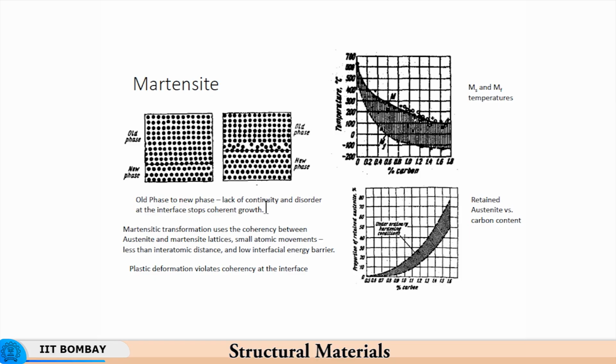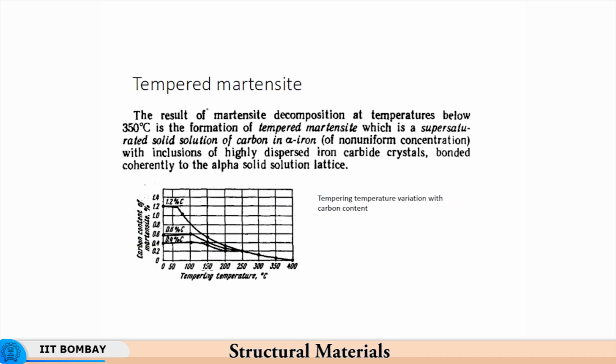So, what I am saying is that the martensite start and finish temperatures are adjusted by chemical composition, and these temperatures enable us to generate strength at the time we want it to have strength. For example, you want the material to be a little softer during deformation, but you want it to be hard, or you want it to get hardened during service. So, that is what happens when you generate martensite at will. And so, the cooling rates and the martensite start and finish temperatures play a significant role.